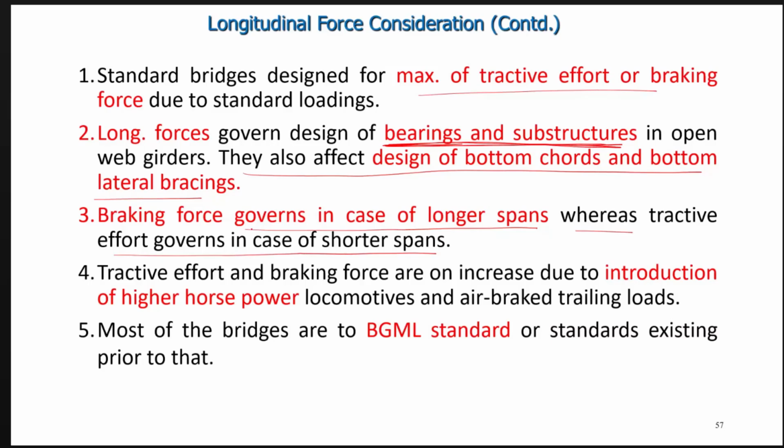As one of the participants asked about the braking force, the same clause applies, because the braking force has been seen up to 50 meters normally in most cases, where tractive force is governing. After that, the braking force becomes higher than the tractive force, because 50 meters means 2 engines, so all tractive force.